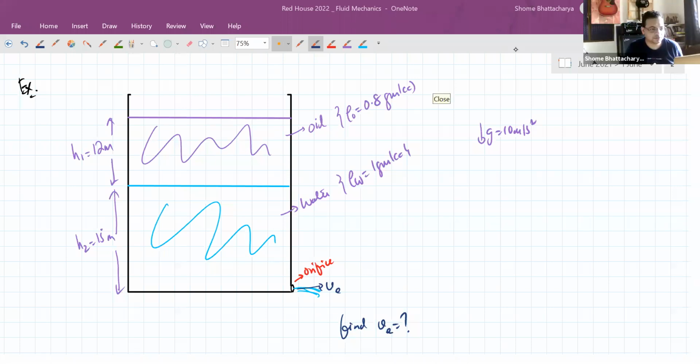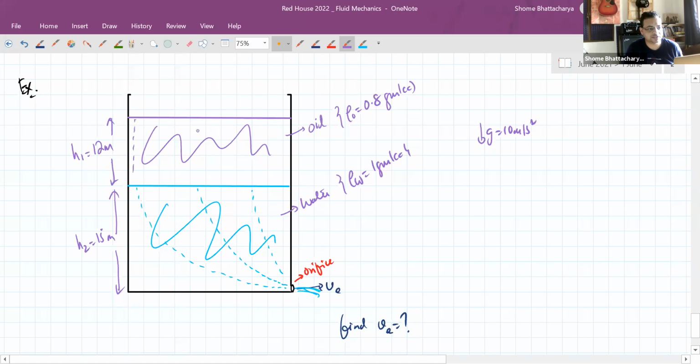So yes, this speed will be something in the range of, I think, around 22 meters per second. Anyhow, let's first understand the question numerically. It's not too difficult, but one thing you have to understand technically is that Bernoulli's equation can only be applied to streamlines across one particular liquid. So I cannot directly apply Bernoulli's equation between a point right at the surface at the top over here, where I know the atmospheric pressure is P naught, and this.